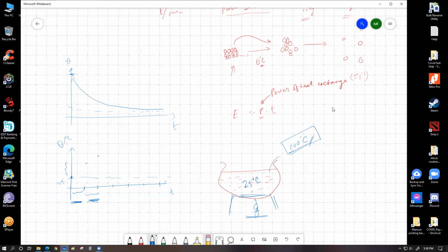The higher the temperature difference between the cold and the hot object, the more rapidly the energy transfer will happen. More rapidly in this case basically means higher power. The rate of energy transfer will become higher. So the amount of joules per second transferred from the container and the water out into the atmosphere will become higher. Because the heat lost will become higher, essentially we can say the heat gained amount or the temperature increase amount should become smaller than before. So let's say in this case, for the first duration of this segment, we had a temperature rise of about 1.5 divisions of this graph.